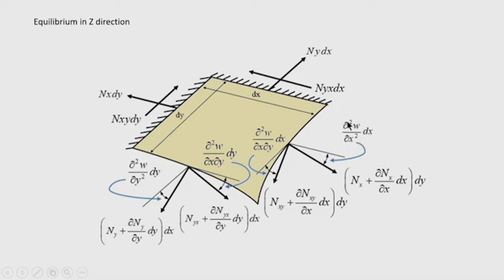So, this is the angle. For small deflection, this is the net slope, because we have clamped this edge. Therefore, we take this as the angle that the normal to the deflected surface makes with the original x axis before the deformation.